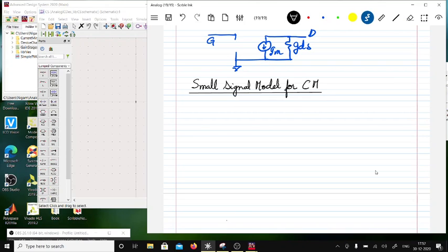Okay, so now the first and foremost is there is a circuit in which I have a transistor which kind of looks like this, right? And its drain is shorted to the gate. This is referred to as a diode connected transistor, right? Now let's see what is the property of this. So if I assume a very simple model like this, then what do I have?